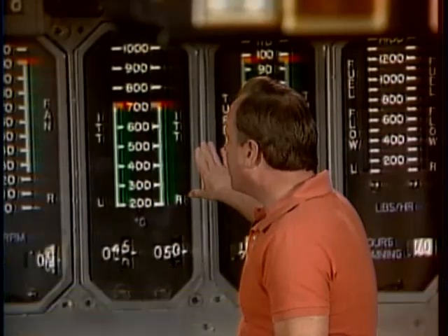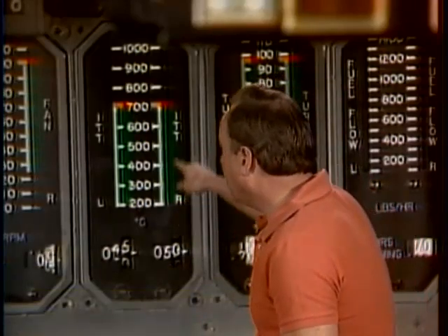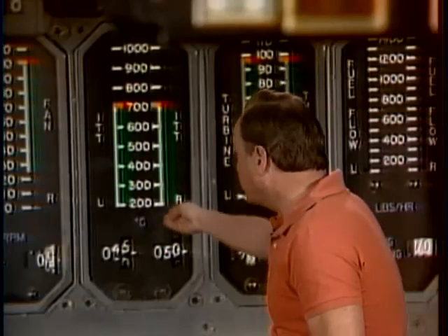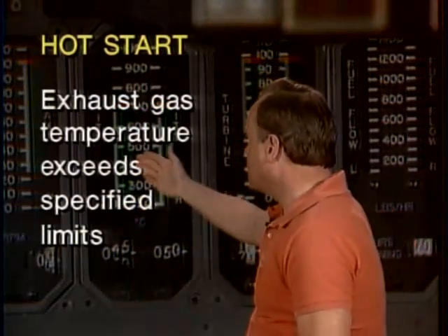How do you tell when you've started an engine? Well, the first indication of starting an engine is you have a rise in the ITT or exhaust gas temperature, either one. So a successful start is indicated by the rise in the ITT. If the ITT or exhaust gas temperature goes too far, then you have a hot start, and a hot start is indicated, according to the FAA, if exhaust gas temperature exceeds specified limits.